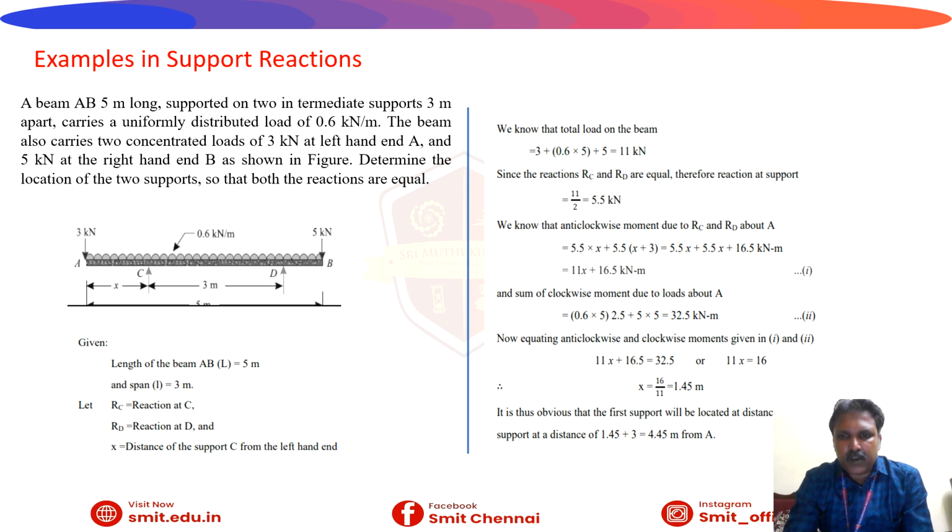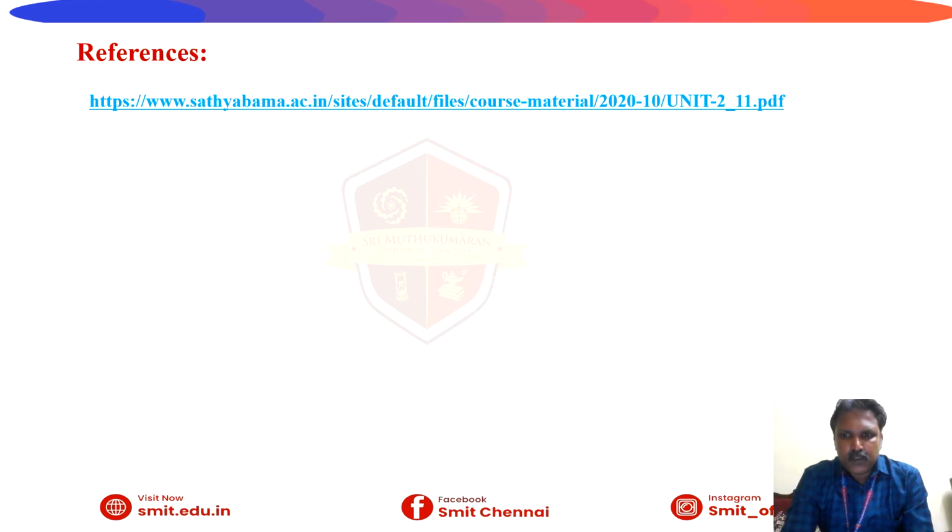Now equating the anticlockwise and clockwise moments given in equations 1 and 2, therefore you will get 11x plus 16.5 equal to 32.5. We are going to equate both these cases. So the first support will be located at a distance of 1.45 meters, where the reaction will occur. So this is for your reference, students.